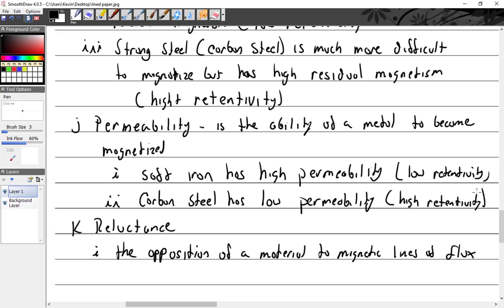Okay, so it rotates in something called pole shoes. Do I want those pole shoes to be strong steel or soft steel? Soft steel. Why soft? So it releases. You don't want it to stay magnetized, because if it stayed magnetized, when the magnet comes back around, it has to demagnetize it and magnetize it the other way.